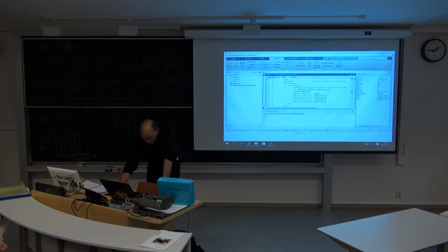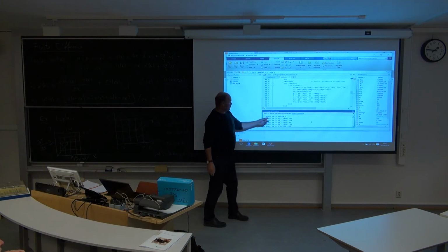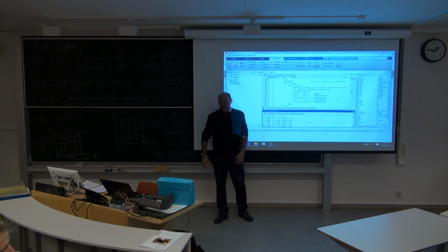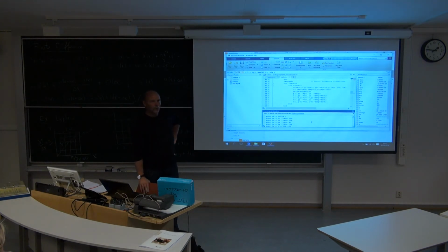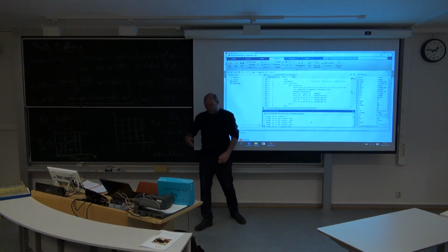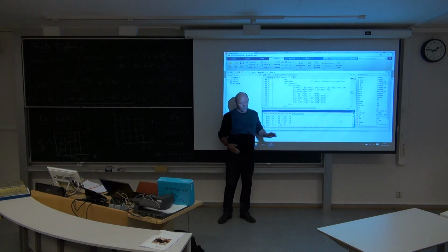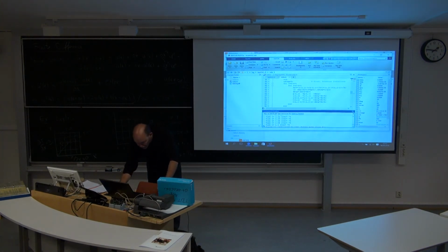So when you are running this SOLA algorithm, I think the default, I can stop it here. Initially, it starts with 128 iterations inside one single time step. Remember, it has to solve the Poisson equation for every time step, more or less accurately. And 128 iterations, that's quite a lot actually, so it takes a long time. But then, as time goes on and the flow starts to develop, there will be smaller and smaller changes for each time step. Then you don't need that many pressure iterations for having the correct solution or the correct time development.